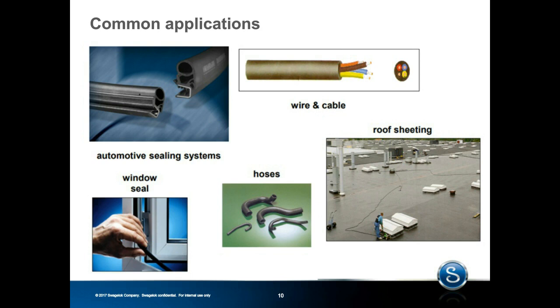It's also used commonly in ponds as pond liner. You see the black sheet liner that's laid down first in those pond or water installations is also ethylene propylene. So when you think of ethylene propylene, think of great weatherability characteristics and not resistant to petroleum-based chemistries.